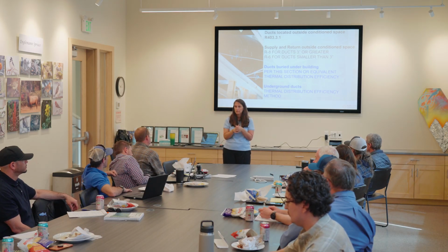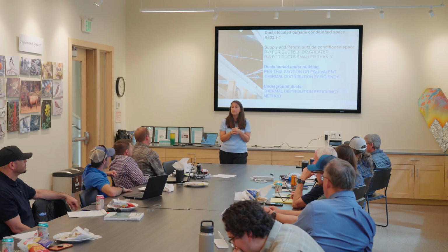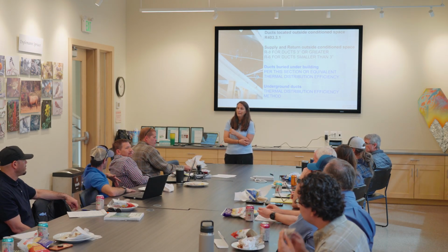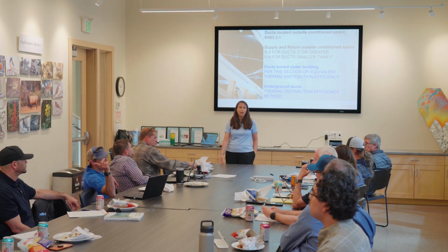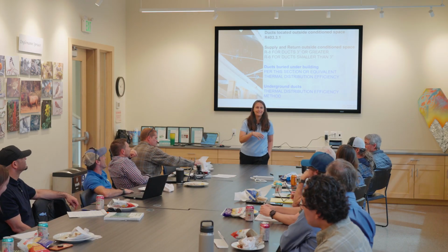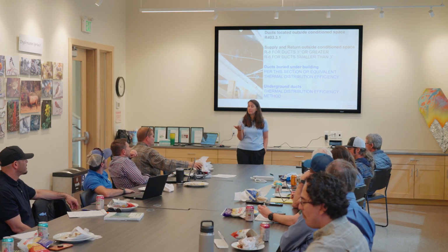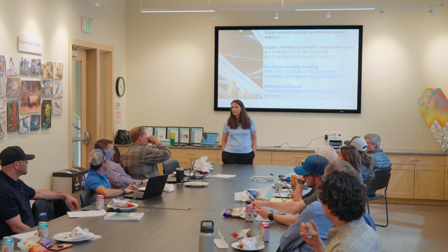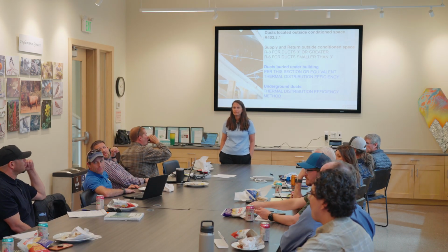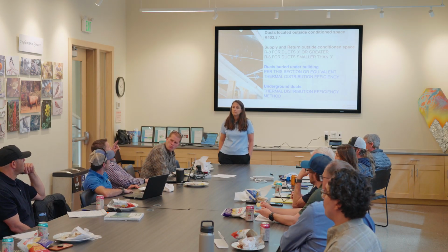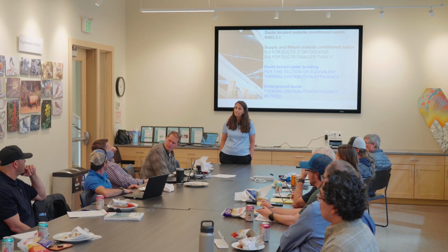I've seen it in single-family homes. You have? In Aspen, no offense to anybody in the Aspen homes, I've seen it, and it's very common. Really? Oh, well, send me examples of it. I'd love to see it. I've also seen it outside of soffits too. Really? If a crossman's too expensive to put in, sometimes they would just do underground ductwork. I worked on two homes, one in Beaver Creek and one in Vail, that had under slab duct systems for heating and cooling.